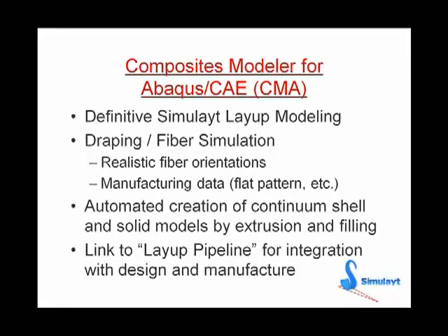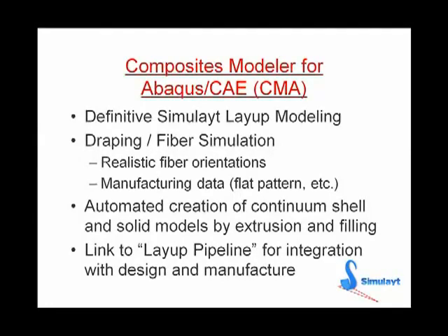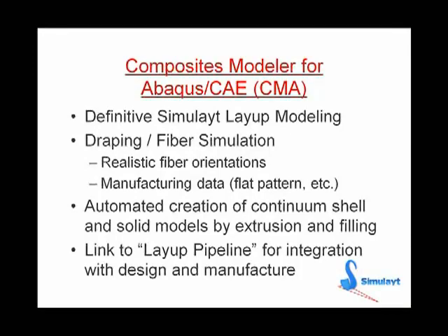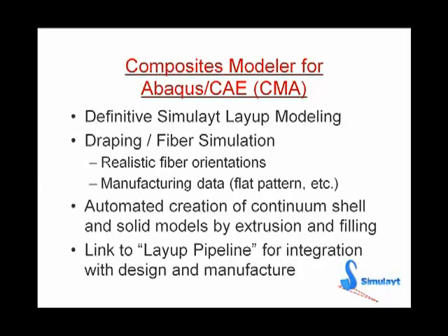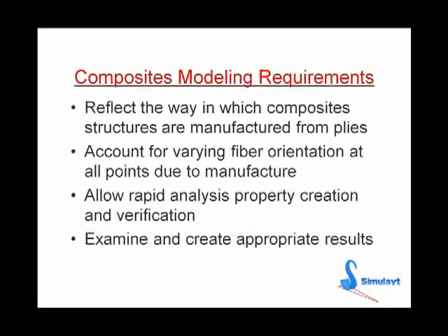CMA provides tools to Abaqus to simulate composites on a ply basis. It includes draping and flat pattern simulation. It also gives a simplified method of adding laminate information for solid elements, and using the layout format, the data is transferable between other applications linking to design and manufacture.